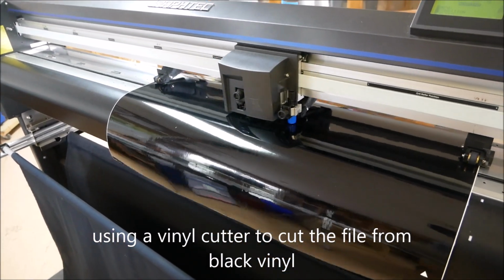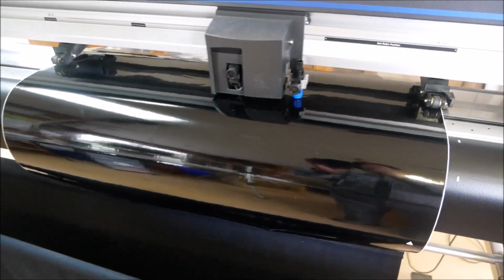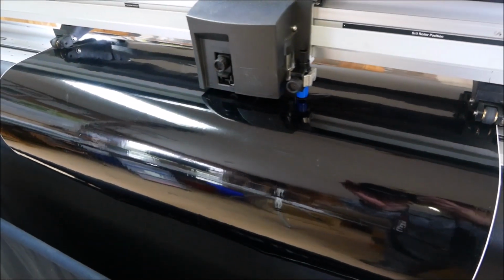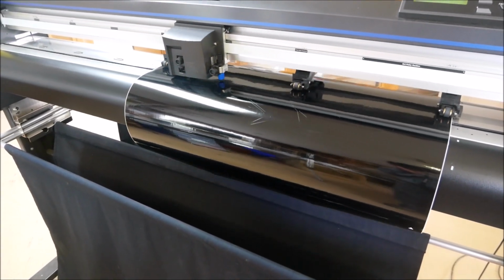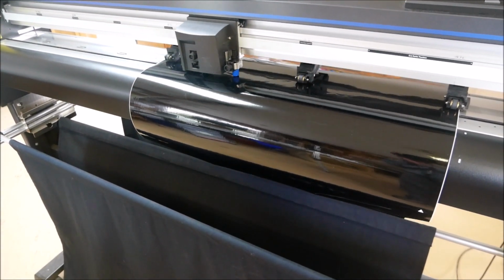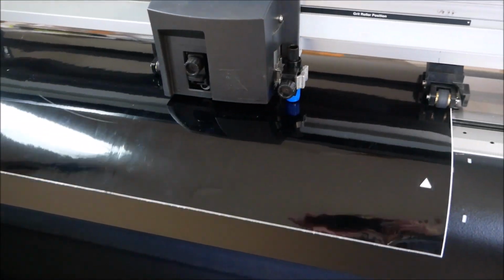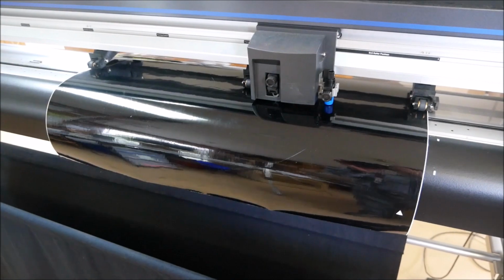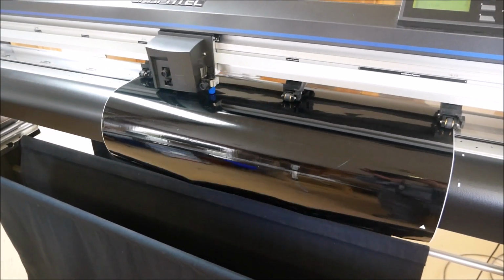Here I've loaded that file that I just traced out into the vinyl cutter. I'm using a 24-inch black vinyl, and I'm going to start my cut. You'll notice that small white triangle in the bottom right-hand corner. That's a test cut to make sure that that vinyl is going to come off the backing. The removal of the vinyl from the backing is called weeding.